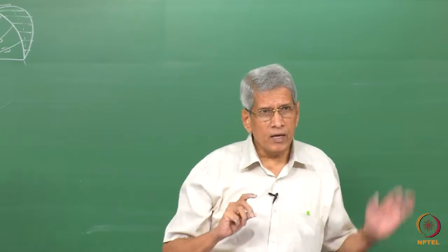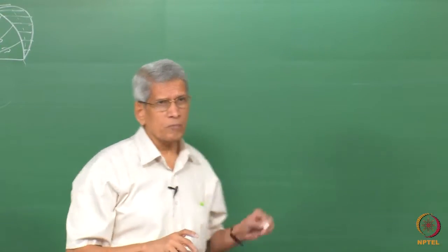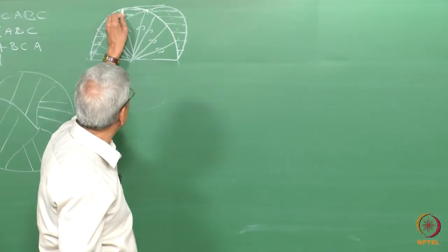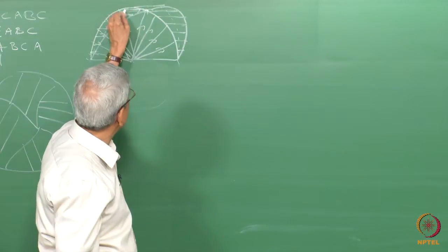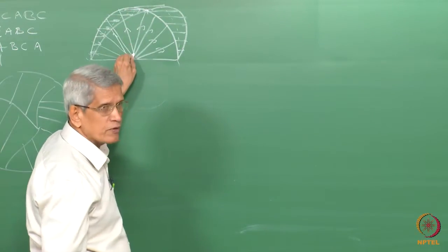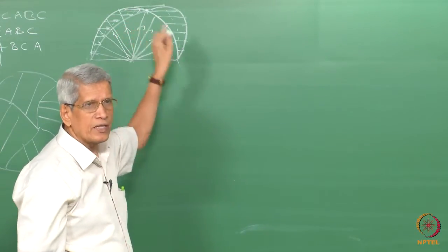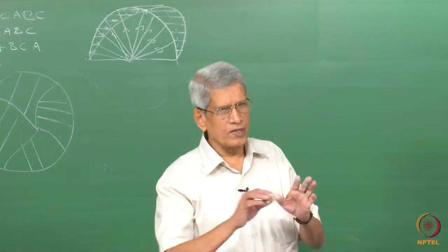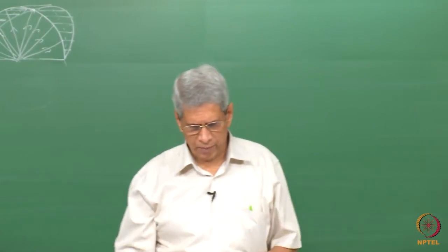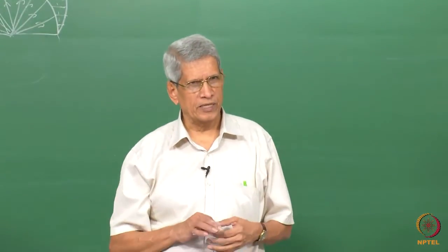But for some deformation, some strain, when that is the shear from here to here, so here to here is the displacement, and this is the height. If we take the ratio of it, that will automatically give what is the simple shear which we are applying. The magnitude of the shear we can calculate.